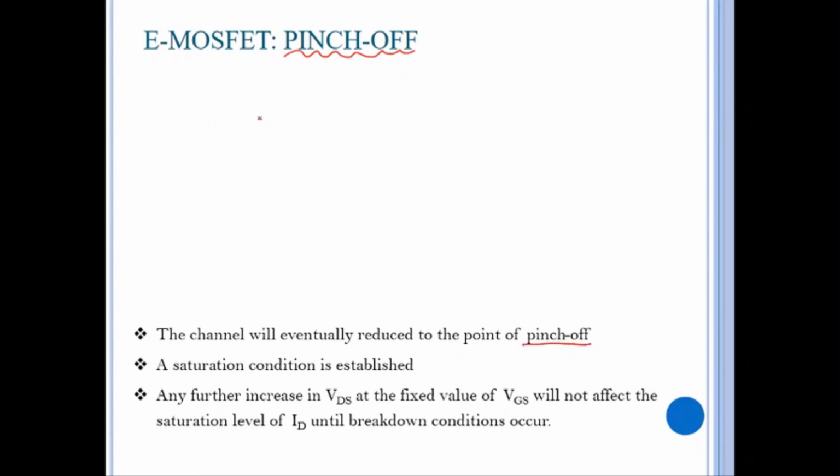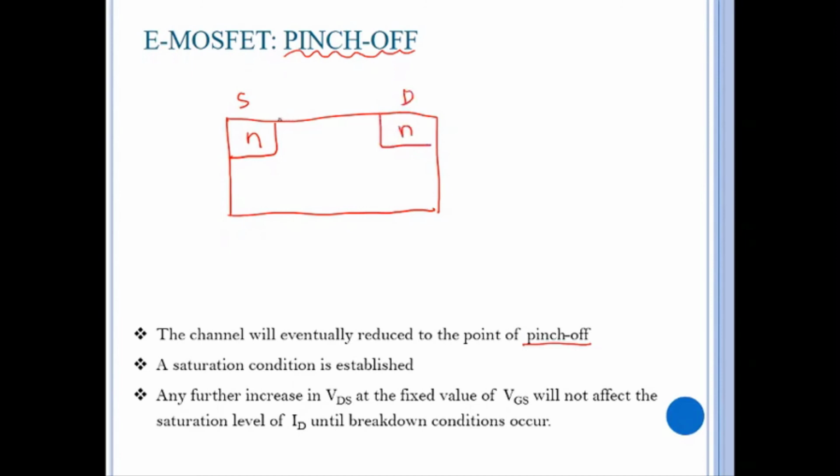So what is the pinch off? So the pinch off phenomenon, this is the n-type source, this is the n-type drain. This is the gate. Okay, the pinch off is where the channel at the drain end is reduced to 0.